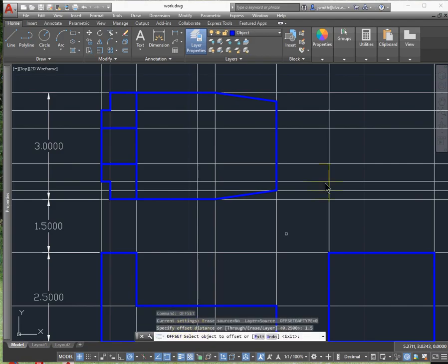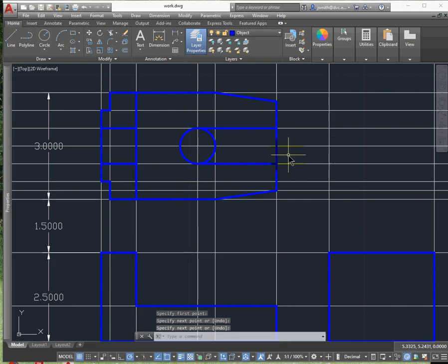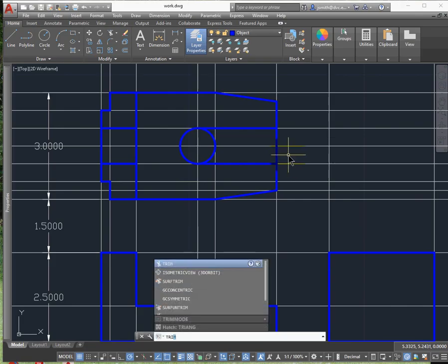All right, so I'm going to put one right in the center that's 1/2 inch offset. And then I'll go ahead and build a circle there. I know exactly where it is, so I'll go ahead and build that circle, snap it to the end, and then go ahead and take my line tool and just snap right on there because I have my ortho snap turned on. And then I'll go ahead and trim these.